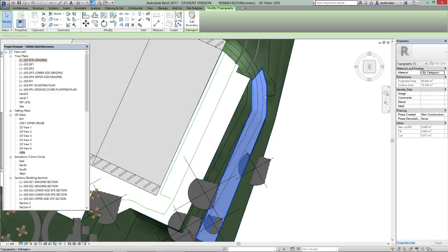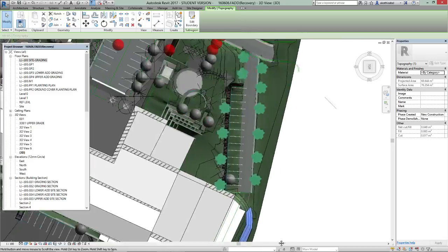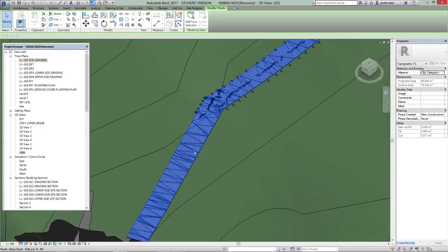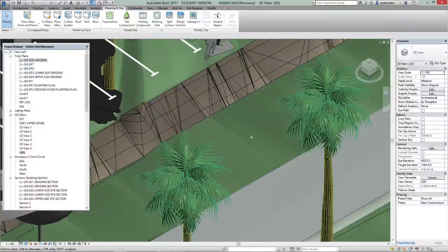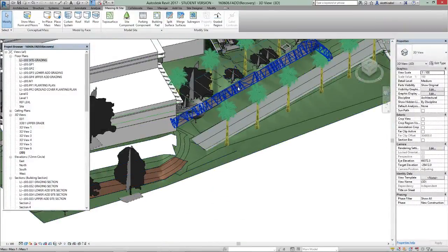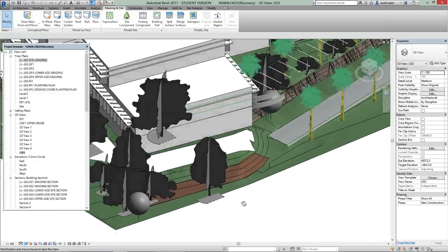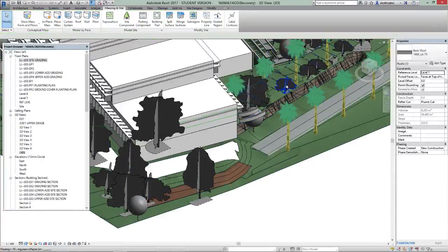So we have a sub-region here where you actually can change the material, but you don't have to necessarily do that. That you only change for the visual of the 3D. If you don't want this kind of visual perception of the walkway with this kind of cubes, then you can have that. Remember the one which appeared in realistic view of this, the rock texture? You can do it here by changing this material to rock. But that is not the main subject of today. The main subject is how do we get this thickness in our detail.